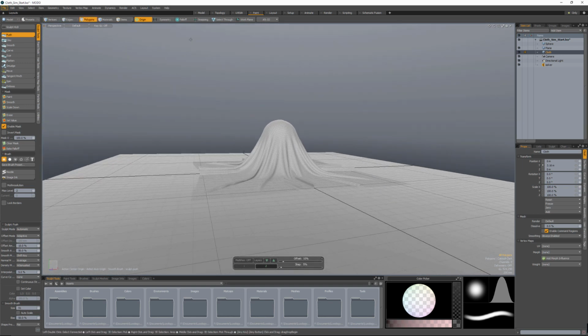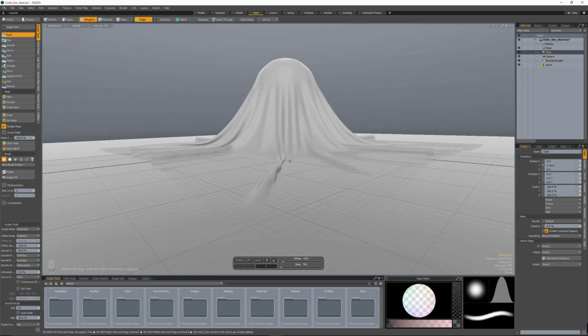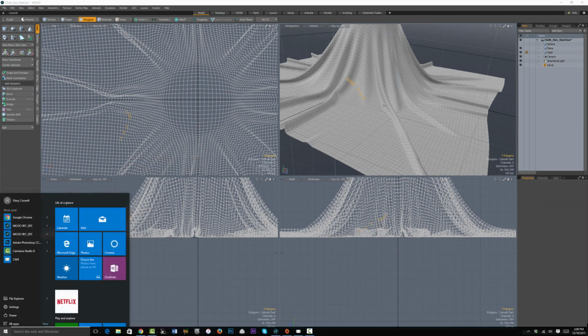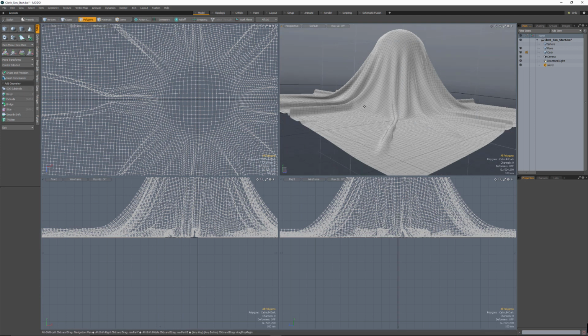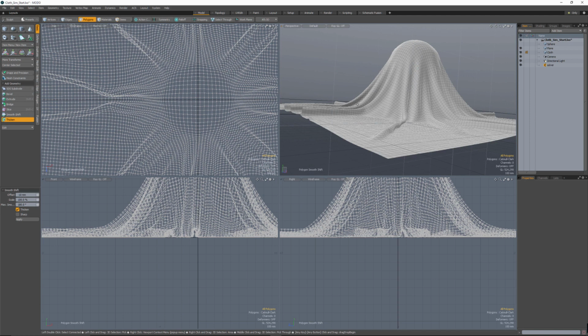And then the final thing that I'm going to do on this is just have something that's a little bit more render ready. I actually want to give it a little bit of thickness. So here, let's hop over to the model tab. And then we're just going to grab this. I'm going to use the thicken tool. And since this is already subdivision surfaces, it's going to be rounded at the edge.